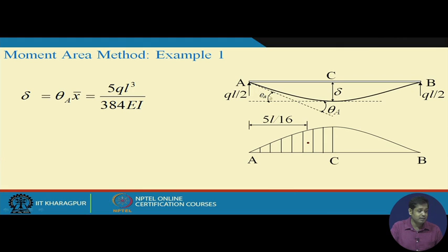In this case, though it is deflection at point C, we are looking at this in a different way. How are we looking at it? We are looking at it as the projection of point A on the slope at C. So, this distance will be the moment of this about point A. So, if you multiply that, this will be the delta for this.